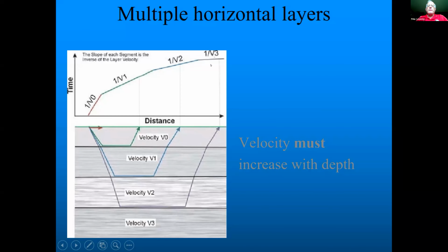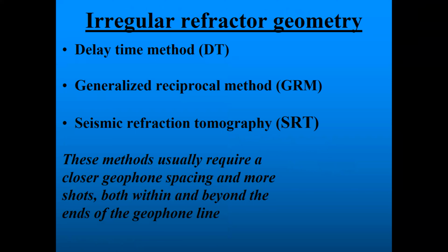Okay. And again, I'll try to fix this PowerPoint so that this stuff is in the proper place. So there are a number of methods you can use: the delay time method, GRM, and seismic refraction tomography, which is what we're using at Orchard Hills to look at the interior of the landfill.